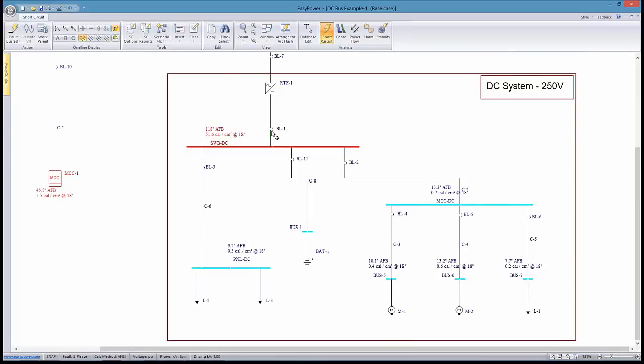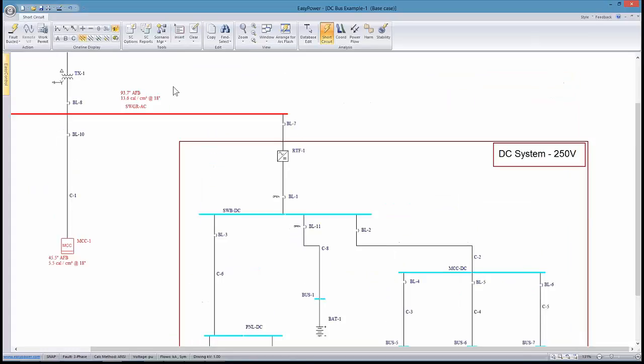You notice that the energy is there whether or not the rectifier is online. This also shows that the breaker for the battery is set too high, because it actually increases the energy downstream if we're powered on the battery. So I guess what this points to is the value of the tools to analyze all the different scenarios that we're exposed to when we have to deal with batteries and multiple sources in a system. Not necessarily the way to design a DC distribution system.